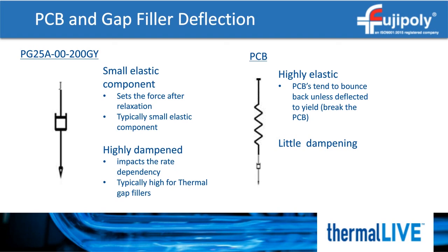are quite different. In the case of our PG25A, which is a very soft gap filler, the elastic component is quite small, but there is a large viscous component. What that means is the force required to compress the gap is higher than the force created when we keep the pad in a deformed state. In the case of the PG25A, the force created by the pad in the deformed state is less than half of the force to compress the pad down at a given rate. In the case of our standard rate, which is about 5 millimeters a minute. Of course, increasing that rate just means more stress.